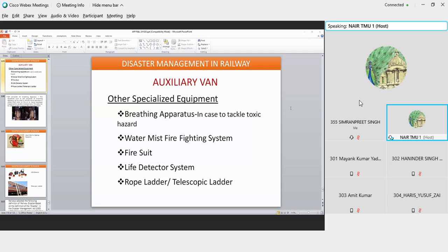Till the time we are able to attend to the rail fracture, a rail piece has fallen down, and the length of the piece which has fallen down is sufficient that the wheel, rather than jumping, comes on a surface where there is no rail head available. In that scenario, yes, the wheel would have a tendency to jump away.